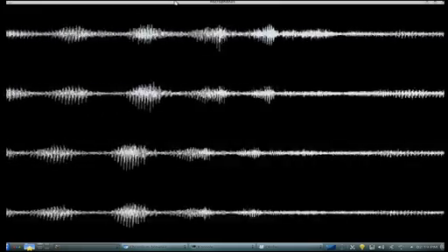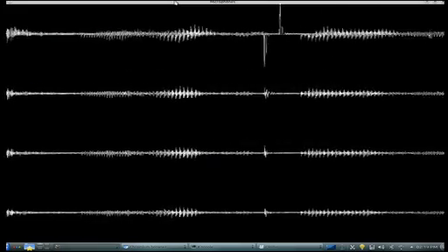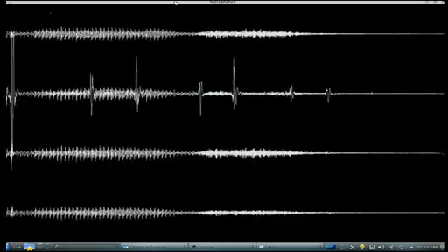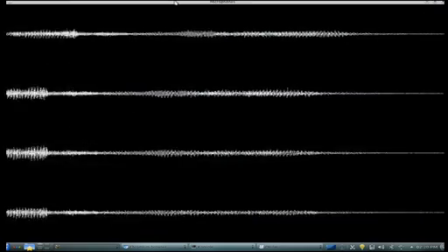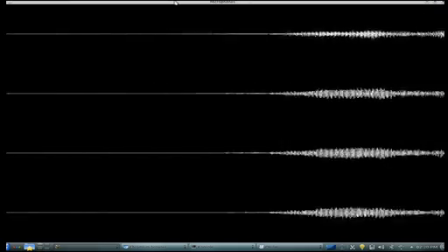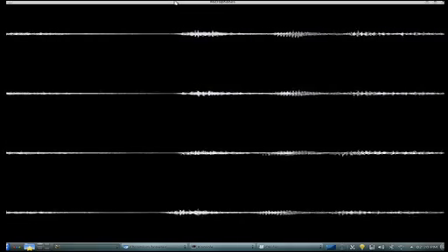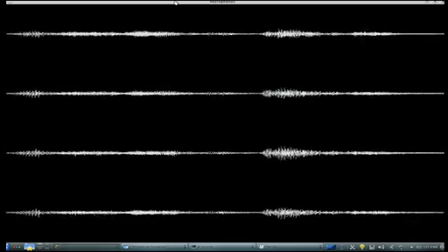And what you see is indeed my voice. It's got 4 microphones. There's one here, and then there's 3 on this side. The Kinect can actually receive what's playing out of the Xbox's speakers. It does noise cancellation. It has a calibration sequence where each microphone's impulse response from each one of these speakers is computed. And so with that, it can subtract out what the speakers are playing, so it can still hear you say Kinect while you're playing your game.